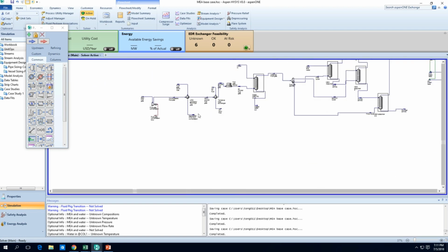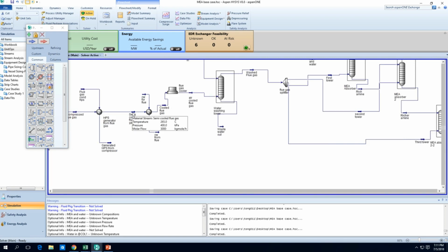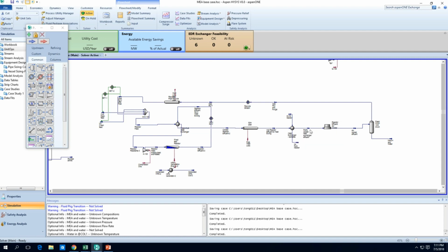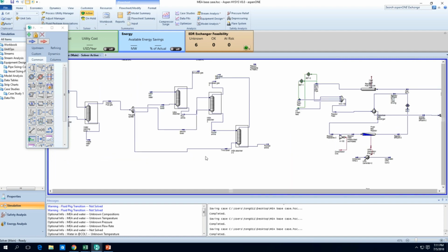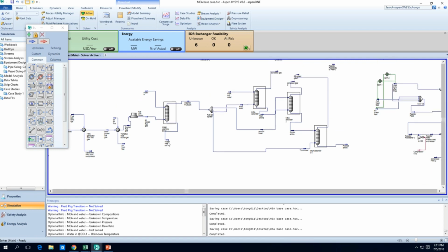And where can we find that heat from? Well, conveniently, we have some of these heat exchangers previously, where we were getting from here 265 degrees C down to 70, and another one here 113 down to 70. So we could take a look at these and see whether some of these can be used.